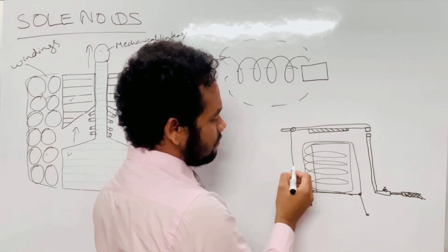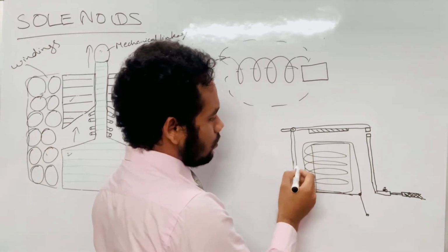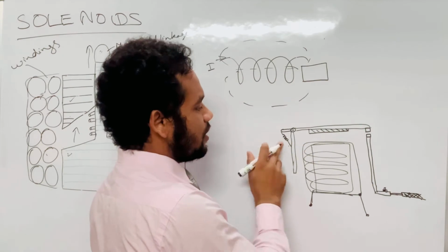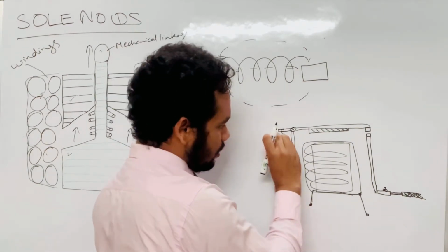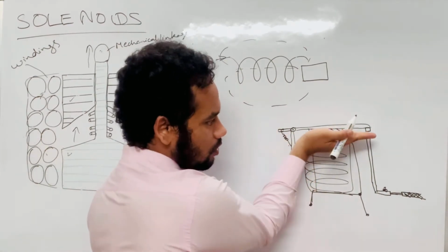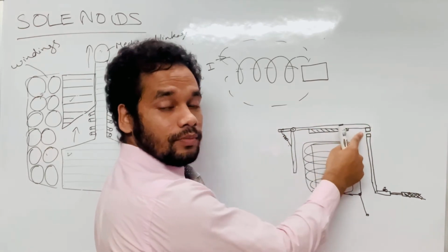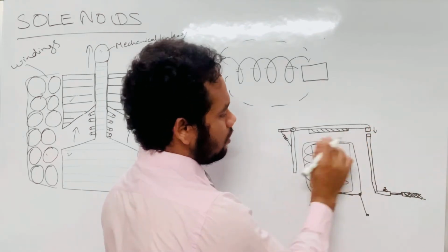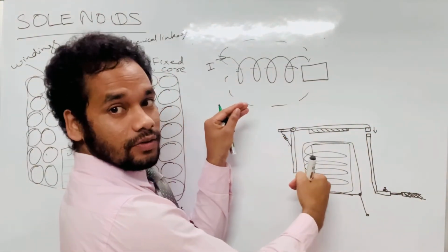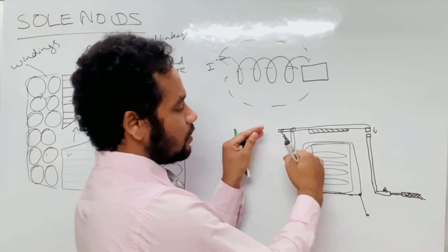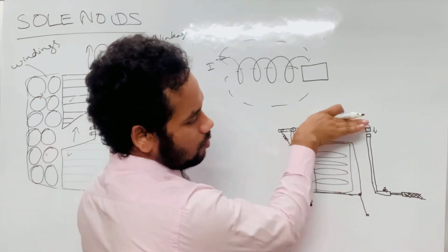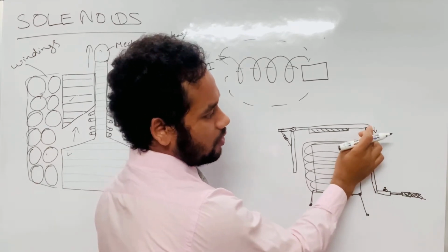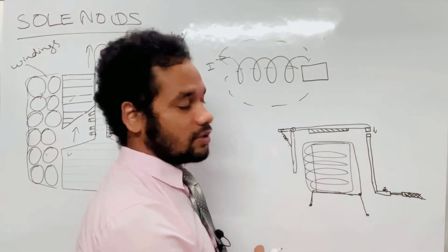And this is another lever on which I connect a spring. Okay, why is this spring there? So that when it is holding its tension, it will cause this contact point to be in the open state. And if I want this contact point to come down, then the spring will extend. So when this has expansion, this will move down, and this contact will touch this contact. So the upper contact will touch the lower contact in that case.